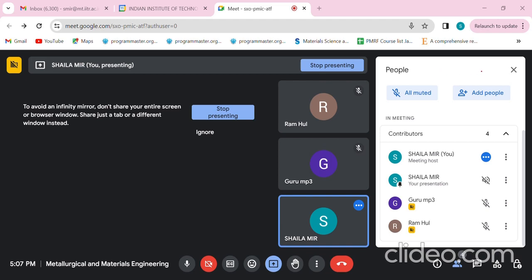Okay. So now we have some numericals to do. The numerical is based on vacancy, right? So we understand what a vacancy is. We have an atomic arrangement of atoms like this. If a certain atom is missing at a certain position, that is called a vacancy, right? This vacancy, as you might have studied, is a temperature dependent phenomenon. It has nothing to do with deformation or any other phenomenon. It is because of thermal excitations that certain atoms get removed from their lattice positions